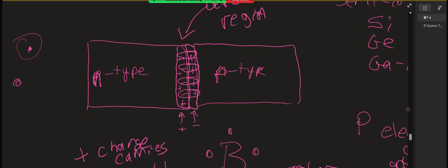All right. True, false. The forward voltage drop of a typical LED is always 0.7 volts, just like a silicon diode. False. LEDs typically have forward drops of 1.8 volts to 3.3 volts or more, depending on the color or material.